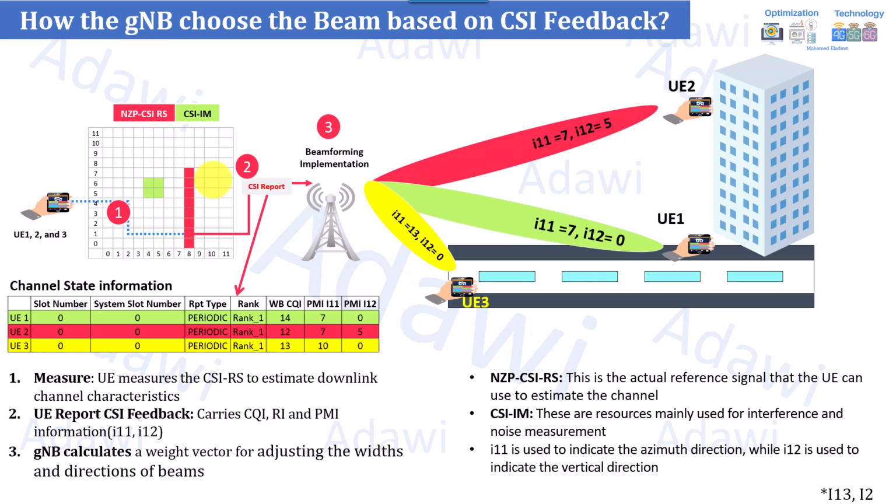If you receive 30 from the user that is not supporting 32, it can still do a dynamic change to transmit only CSI-RS, because CSI-RS is a kind of dedicated resource coming only per user demand. But this is the first part. We'd like to check how to check the capability of the CSI-RS, the maximum number of supported CSI-RS ports.